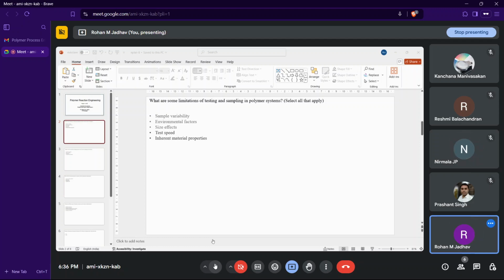Yes, ma'am. Fill factor is an important measurement that you can use to evaluate the efficiency of how the mold is being filled. If your fill factor is low, superficial filling of the polymer can happen during injection molding, and because of that, the polymer may not flow properly in the cavity. So your fill factor should be a bit high so that the material can properly flow into it and your injection polymer is produced in a better homogeneous manner. So that's what fill factor is.